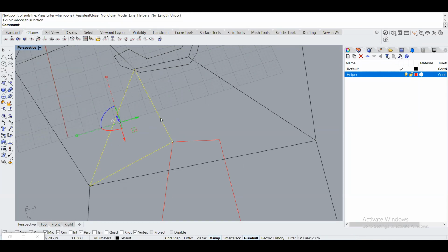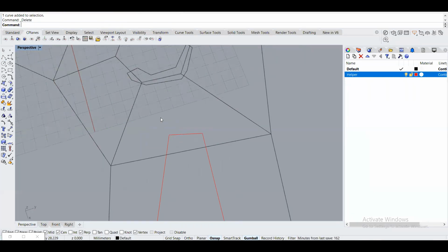Every single patch that you do needs to be rectilinear, meaning it needs to have 4 corner points. If it has 5, it will not work. If it has 3, it will not work. That's the limitation. It is possible to make it work with 3 or 5 corner points, but first be able to use this definition well, and then if you need to, we will be able to implement more functionality to it.